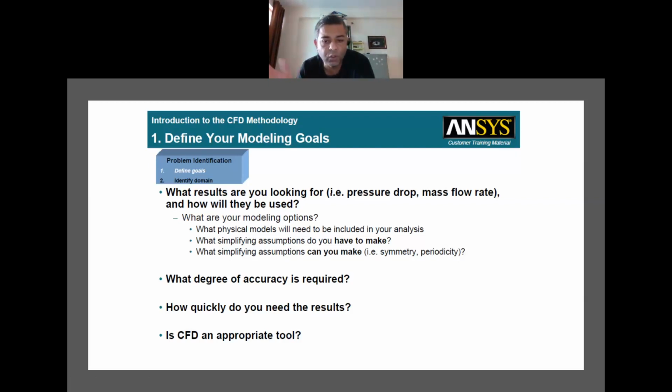No need to do for other parts, because this is a very time consuming process. So as number of meshes will be less, it is good for you. Also system requirement is very important. If the big model is there, it will not run in normal system. You have to need a RAM of around 100 GB or something like this for bigger or larger mesh systems.